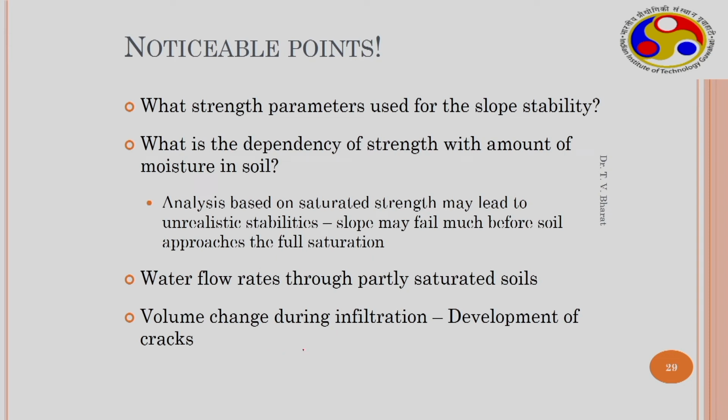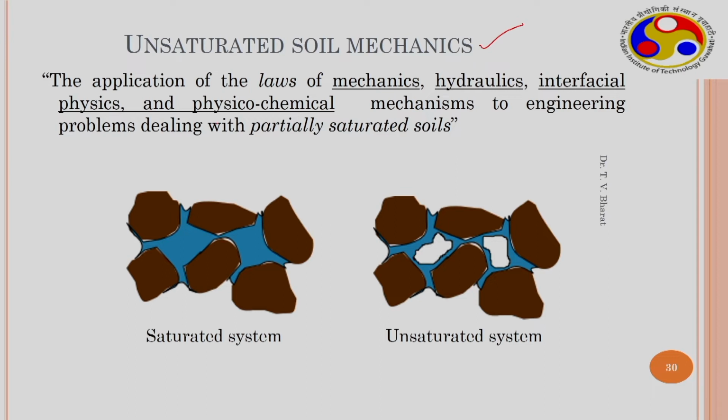And the third aspect is the volume change behavior during infiltration of water under a given normal stress, normal load, and development of cracks due to volume changes. These issues can be well addressed using unsaturated soil mechanics. Therefore, unsaturated soil mechanics should be defined as the application of the laws of mechanics and hydraulics, which are anyway used in basic soil mechanics, with additionally interfacial physics, so you can allow the surface tension forces to come in and explain many things, and physico-chemical mechanisms, so that you can address fine grained soil behavior, to engineering problems dealing with partly saturated soils. With this I'll stop here, and I'm sure this would provide enough motivation for studying this subject.